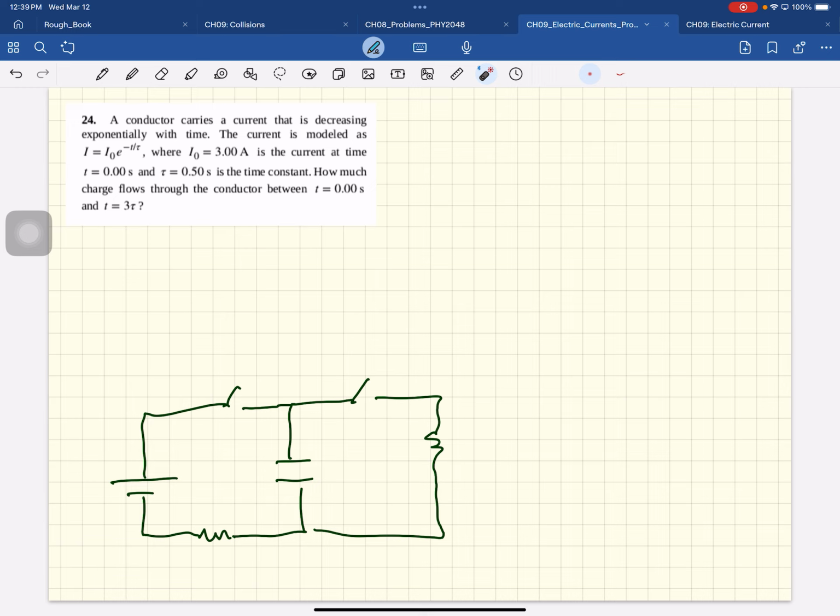And for instance, this is a defibrillator circuit like this. This is the flash camera circuit, it is like this. So when you close the switch, the capacitor gets charged. And once the capacitor is charged, you can open the switch. And now you're ready to take a picture or you're ready to restart a heart. This can be a heart, this can be a flash camera.